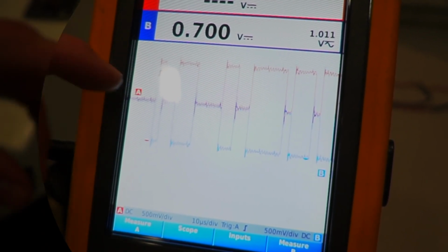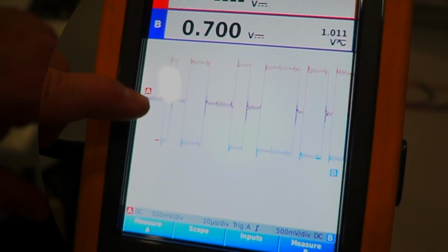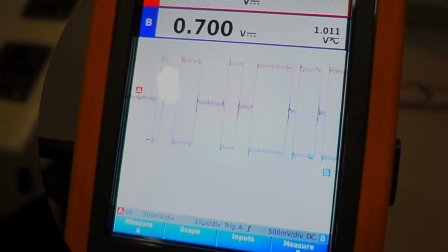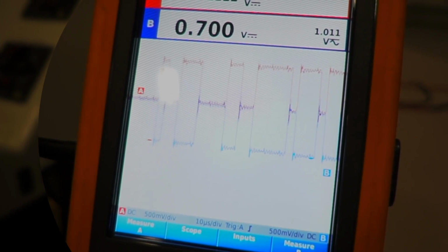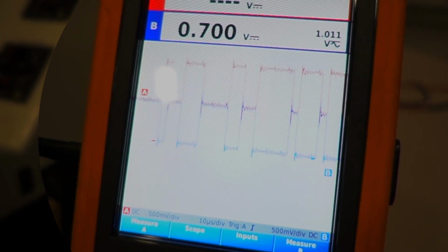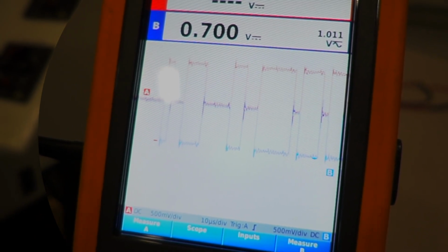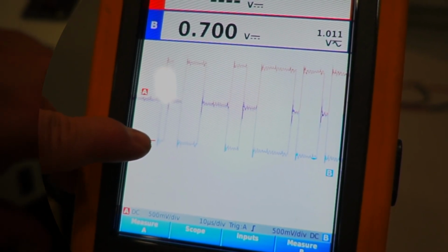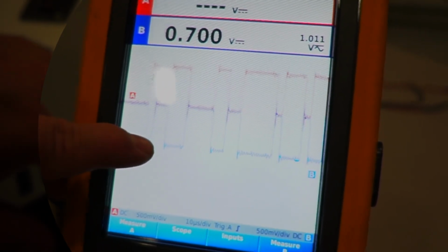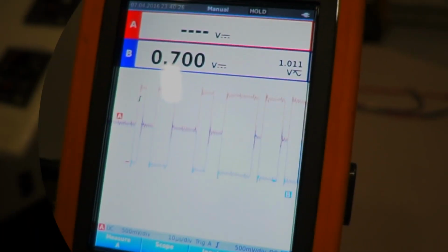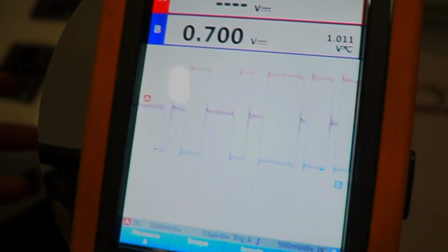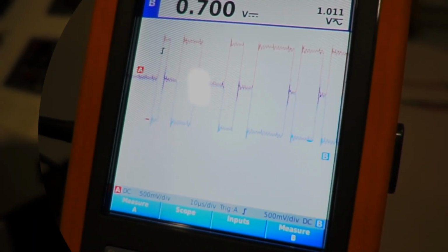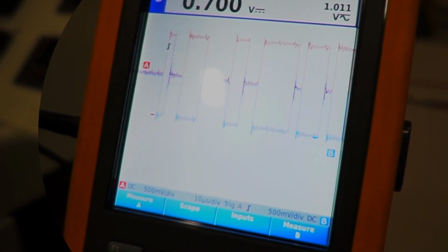the way the chip is going to read that is as a bit zero. And then when the two voltages go back together down here to the same level at 2.5, the differential is around 0 volts, and so the chip is going to read that as a bit 1. So this is 4 microseconds here, that would be a 0. This gap where they're both back together again is about 8 microseconds wide, so that would be 2 ones, right? It takes a sample every 4 microseconds.